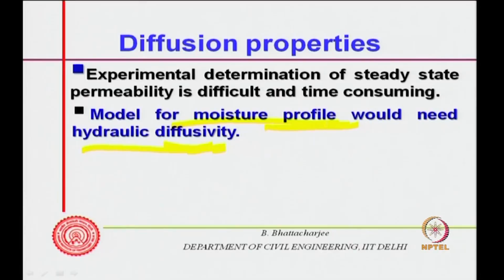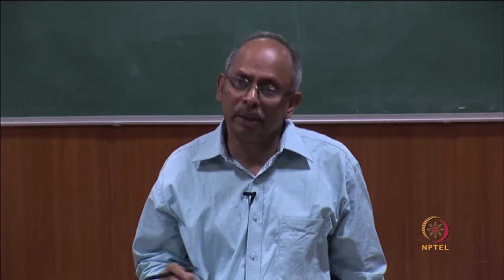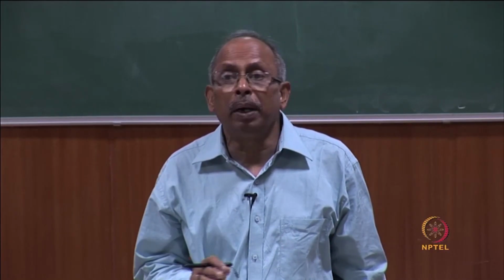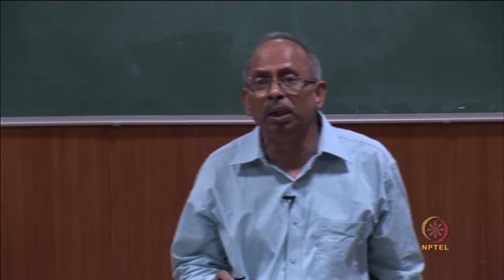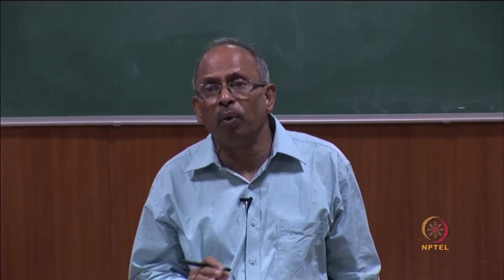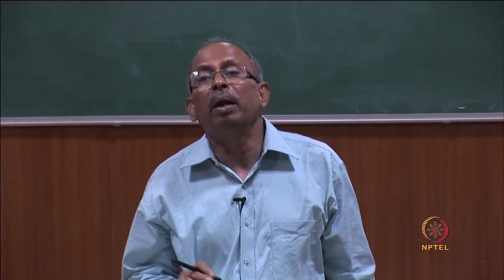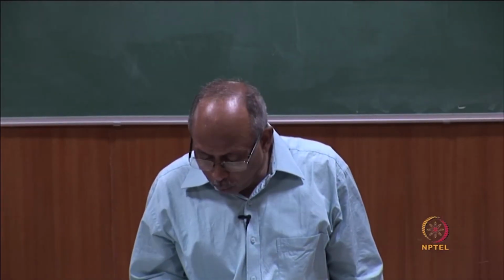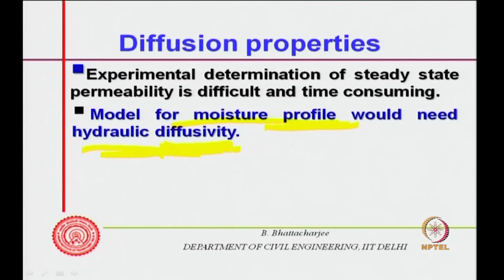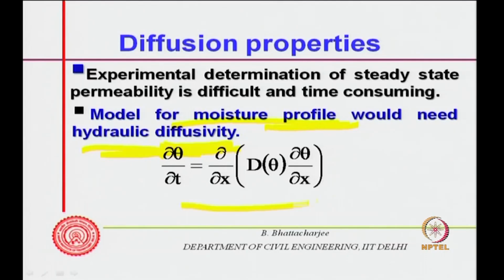But here the diffusion of oxygen, carbon dioxide, all these will be concentration dependent, but water diffusion or hydraulic diffusivity is not exactly diffusion; it flows under capillary suction or under a vapor pressure gradient. So, for the water situation, one can use hydraulic diffusivity, and the equation that governs this liquid water flow, or a similar equation that even governs vapor flow, is called the Richards equation, right. D theta is a function of the degree of saturation itself.